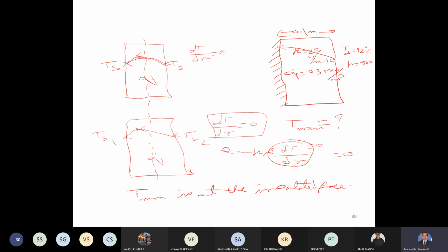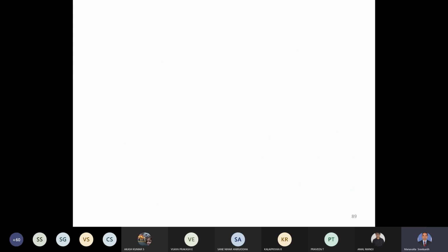Now we will use the equations that are available for us to solve this problem. We derived these during the theory. Now we have steady state heat conduction with heat generation, and for that we have the outside convection conditions. I am referring to page 56 of the data book. On page 56, we have one equation for TW, the wall temperature: TW is equal to T infinity plus Q dot L by h. T infinity is the fluid temperature, Q dot is the heat generation rate, L is the thickness of the slab, and h is the heat transfer coefficient.